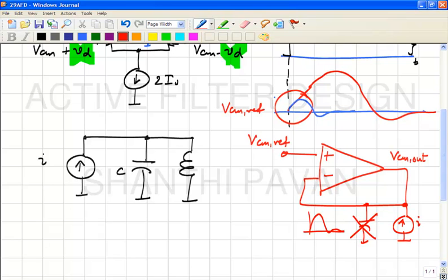So, you pump in some current, suddenly the voltage rises, and then the feedback loop figures out that there's a difference between the reference and the output and does whatever it takes to fix the output voltage. This takes time, right? But during that time, the output will jump up, and depending on the speed of the feedback loop will eventually come back to 0. Is this clear?